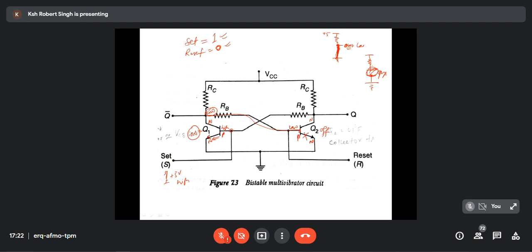If the switch is open, then what will be the voltage over here? The voltage over here is 5 volt. The same 5 volt will appear here. It is open. Like when you have a battery and just measure the potential difference, this is plus, this is minus, 1.5 volt will be there. No wire is connected, you are just measuring open. So if the circuit is open, even though there is resistance, no current will flow, so there will be no drop.